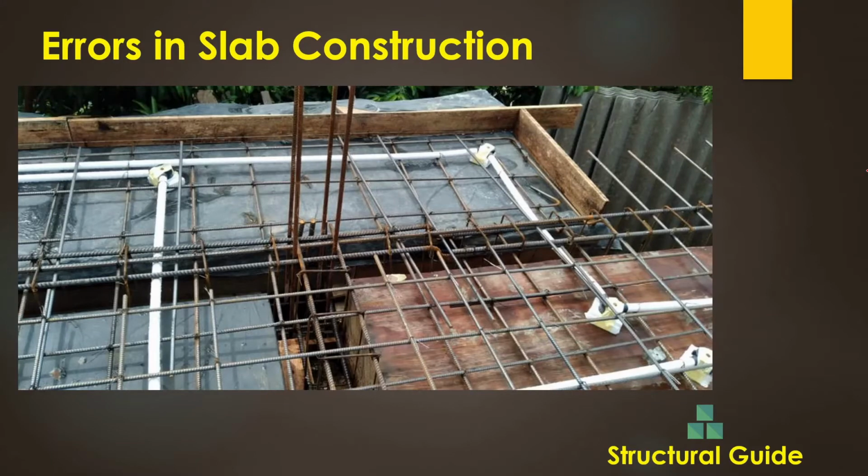Errors in construction: not providing top reinforcement, inadequate anchorage length, incorrect cranking of reinforcement, lap positions, correct lap length. We need to discuss what are the correct methods you need to follow.